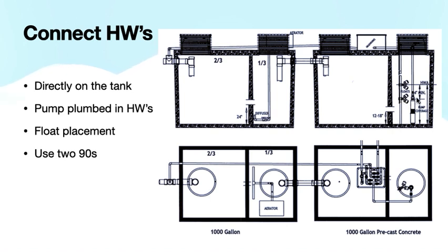The bottom float, we just want drilled at the same elevation as the top of the pump. The idea being that with the float being there, the pump is always going to be submerged in water. That's the goal. The top float here, we just want a minimum of 4 inches, but I'd say anywhere between 4 to 8 inches above that, and that's your working volume. And this top float is just your high water level alarm float. But those are those floats there.